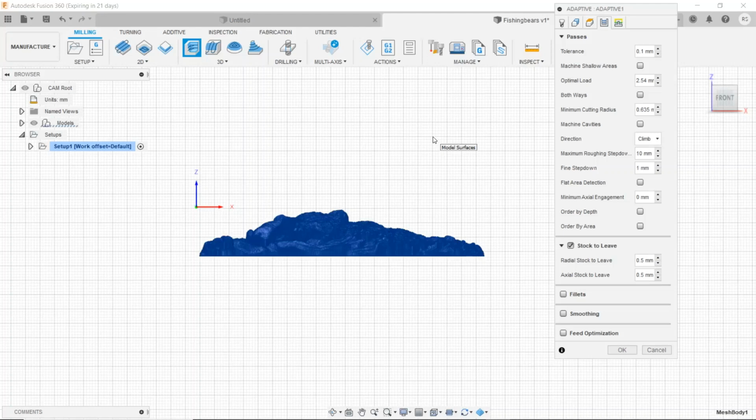The max you can cut with a 1/4 inch end mill is 1 millimeter to 1.5 millimeters max. If you ever go past 1.5 millimeters, you're on your own. You will vibrate your machine to death. You'll wreck all the guides and everything, and do not do it. So, based on that note, I want to take a 1 millimeter cut with my 1/4 inch flat end mill. So that's 1 millimeter deep.